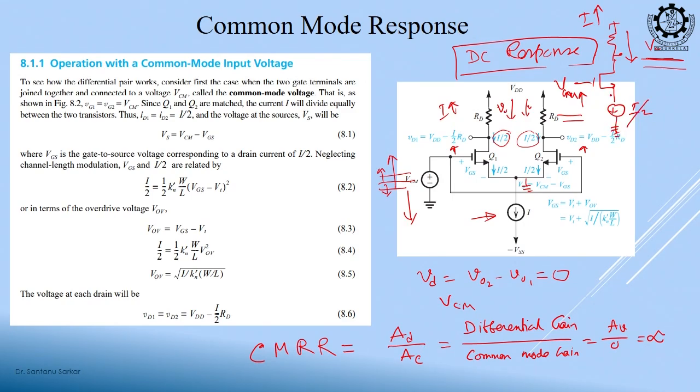So, this current will tell this current, okay, you are fixed now, you cannot change. So, even if my DC voltage is varying, this current cannot change. Why? Because this is forcing it. What is the meaning of constant current? Even if the voltage is changing, current cannot change, that is the constant current. So, this current is forcing this I, that you cannot change.